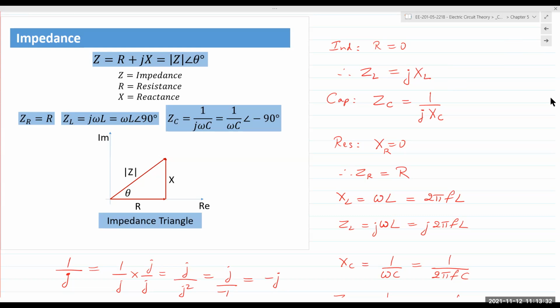In theoretical analysis, inductor resistance is equal to 0, right? So it's simply a short circuit, allows the current to actually pass through. Energy is stored. That energy generates a back EMF or a voltage that opposes the initially flowing current. And so if you try to change that current, that stored energy is going to oppose any change in that current. So it's not direct opposition. So resistance is equal to 0, but any opposition thereafter to oppose any change in the current is represented as the reactance. So it has a physical basis in real life, but mathematically we say it is imaginary. Does that make sense to everyone?